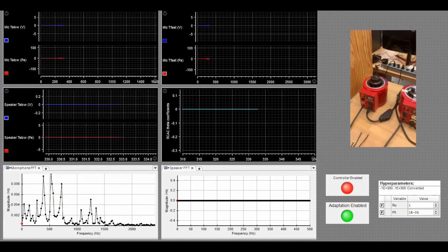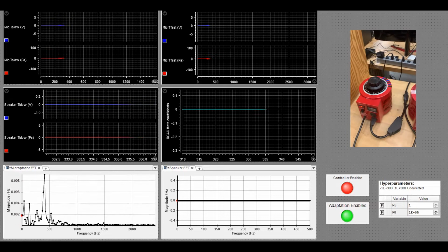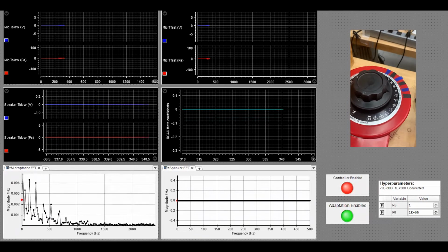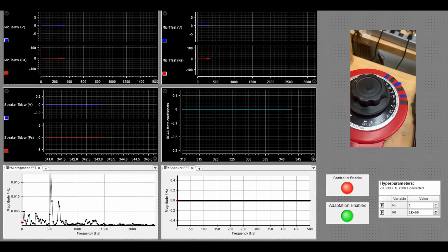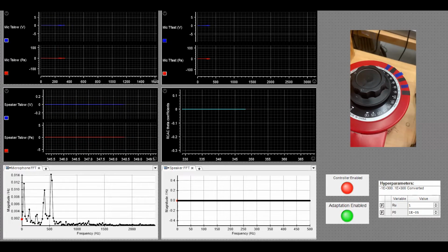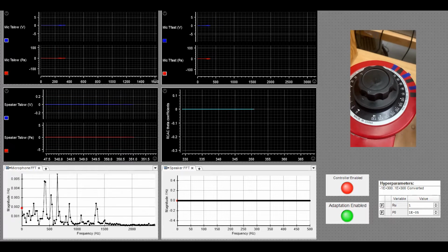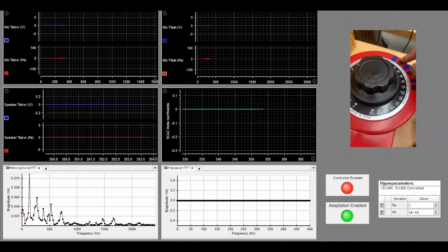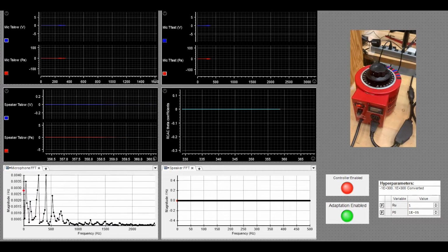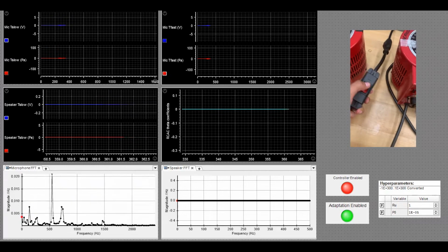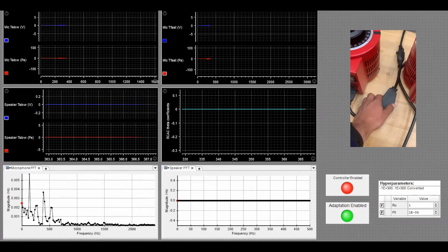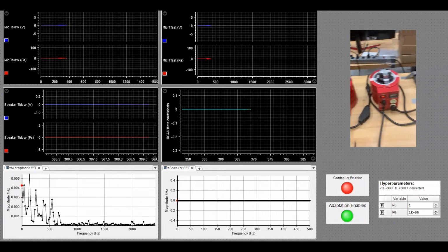Finally, here you see the variac, which we are going to use to supply energy to the coil. Here you can see markings in blue and markings in black. The markings in blue mark the voltage levels for other tests that we were performing before. We will be performing tests on 75 volts and 95 volts today. And finally, here we have the switch, which will allow us to send electrical energy to the coil. Now we will proceed with the tests.